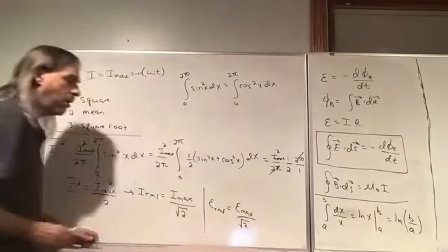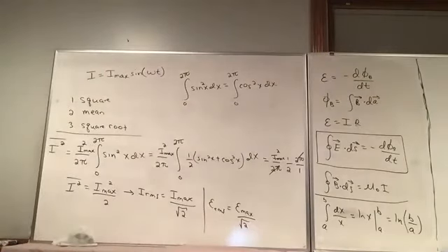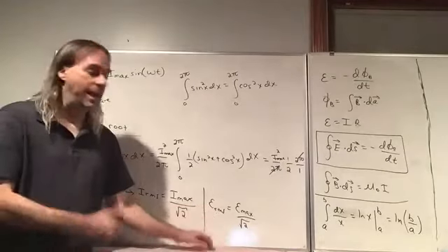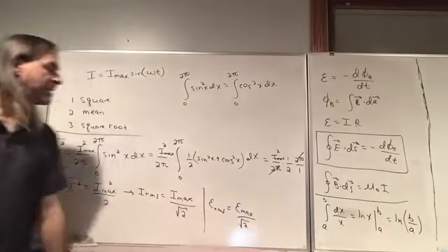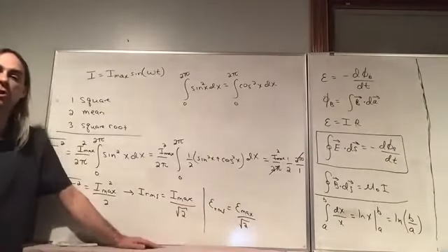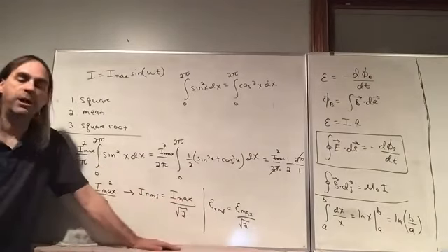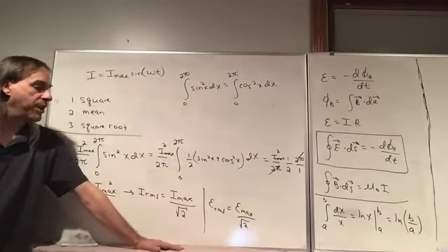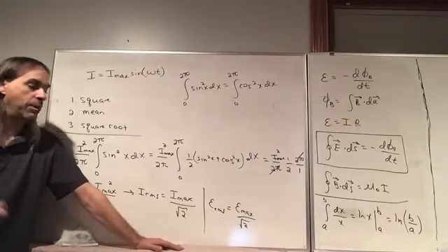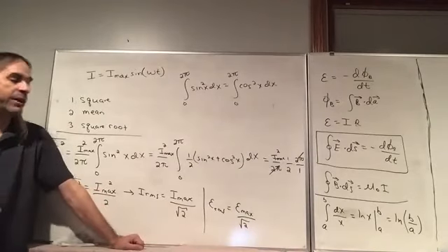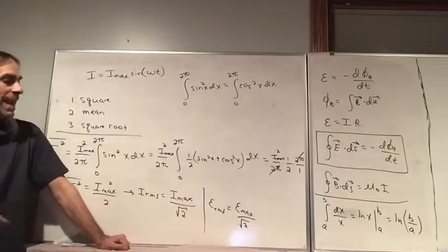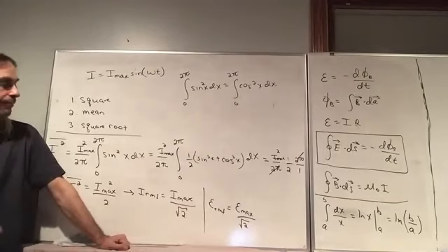The RMS value, let's just say average voltage you get, where we understand we mean the RMS value, is the peak value over the square root of 2. So the maximum voltage you get from an outlet is typically around 170 volts. It's the RMS average that's 120.